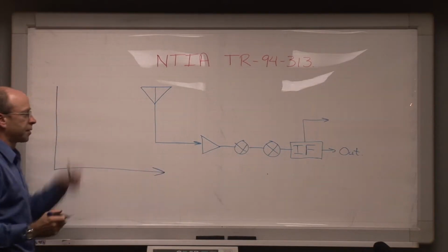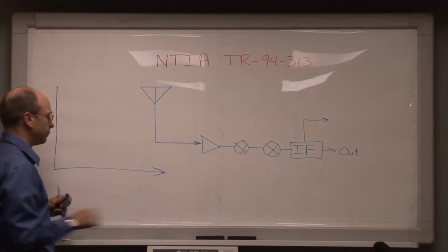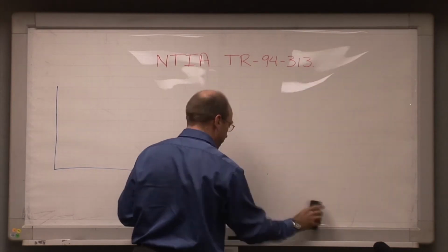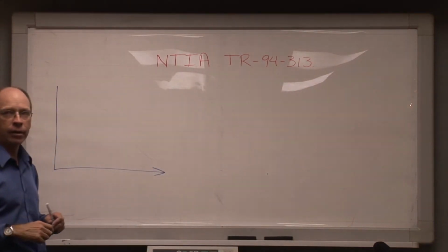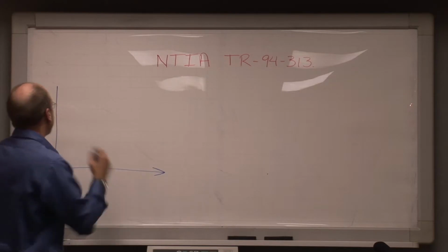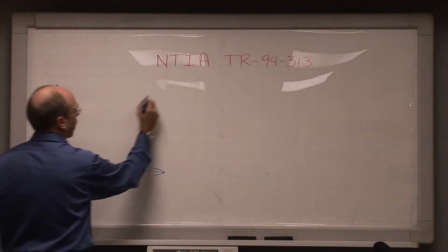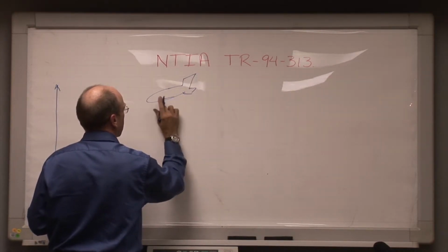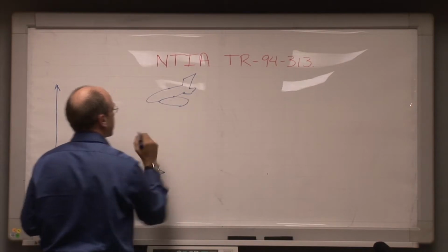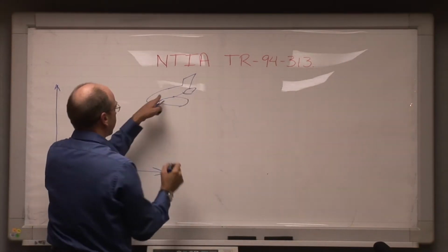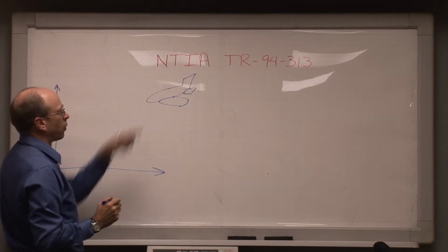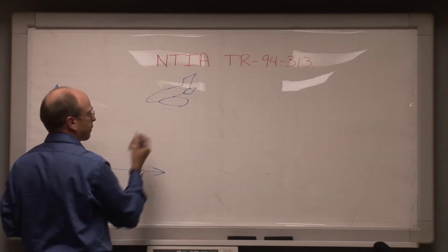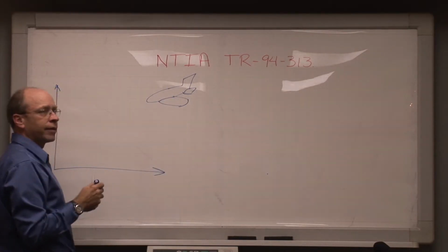If the transmitter is near the receiver, then you can go directly to the transmitter site, presumably from the receiver site, and make the spectrum measurement either with a truck or van vehicle like NTIA has or with a suitcase system. In other cases that we have encountered, where an airborne system of some sort has been identified as causing the interference, you might need to actually find the airborne system, go to a location where you have these aircraft on the ground and have them turn on the transmitter, say it's a radar, from the aircraft on the ground. In any event, you need to measure the spectrum.